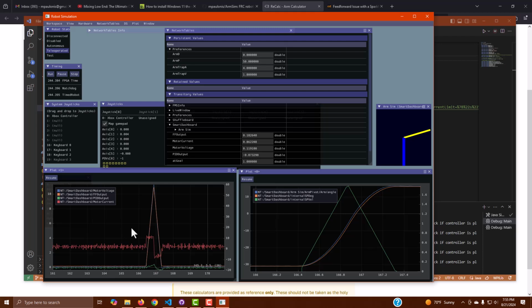But then we see how did this arm track the changing set point. And it did it mostly with feed forward. So feed forward here is the orange color. It looks like that went up really nicely. And the feedback, which is green, had to do almost nothing because the feed forward was really very accurate. So the total voltage is almost identical to the orange.